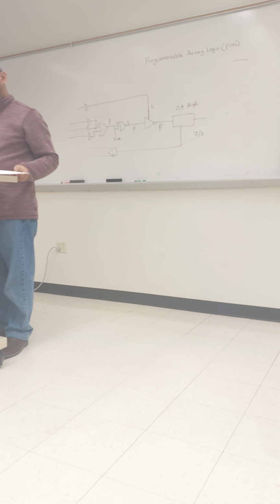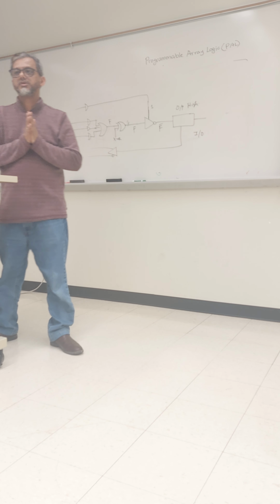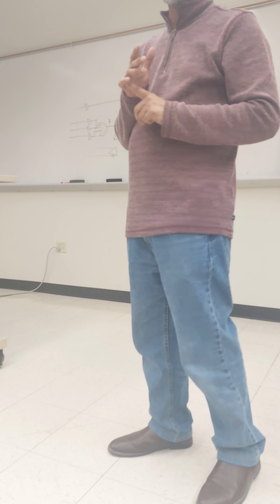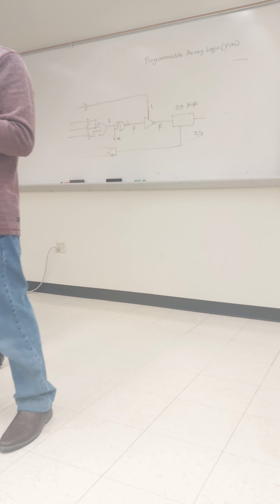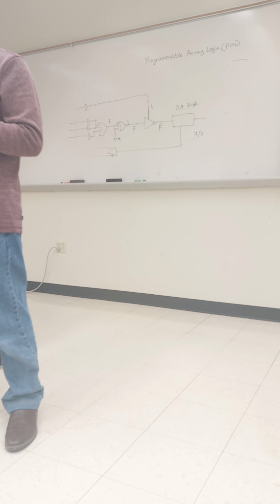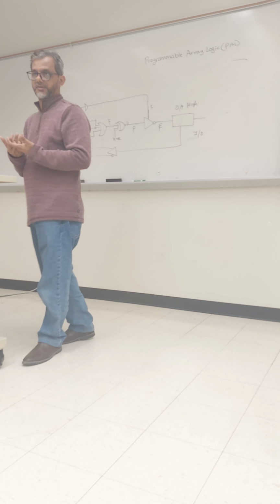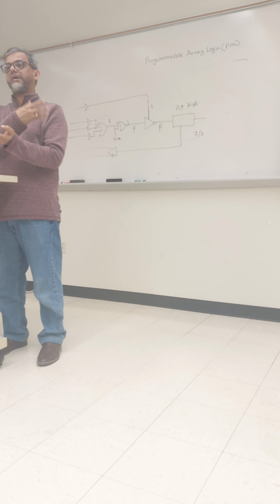If we want to increase more functionality, for example, so far we have talked about PLD, programmable logic devices. We talked about PROM, we talked about PLA, we talked about PAL. All of them are combinational circuits. None of them are sequential circuits. That means none of them have any register. None of them has any memory cell. But in the commercially available PAL, they also have a register circuit. That means they are sequential circuits. They can store, they can give the feedback, they can give you the information back. That is the feedback, right?